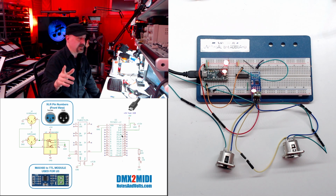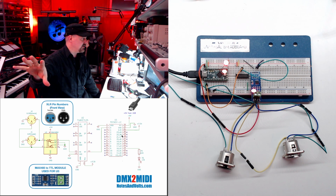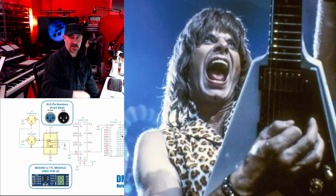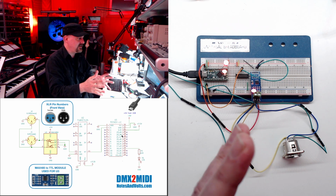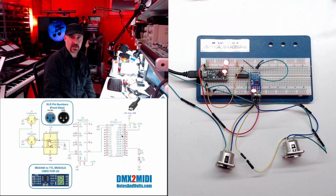Now that is great because if you think about the average stage setup, the lighting guy is probably at the back of the room and the stage has got all the lights, so he has to run a cable all the way there, and there's people jumping all over the place and rock and roll guys with their electric guitars causing all sorts of interference. So there's a lot of chance for that signal to get messed up. But the RS-485 protocol kind of keeps that signal clean, so it makes it all the way to the stage and you can enjoy your rock and roll performance.